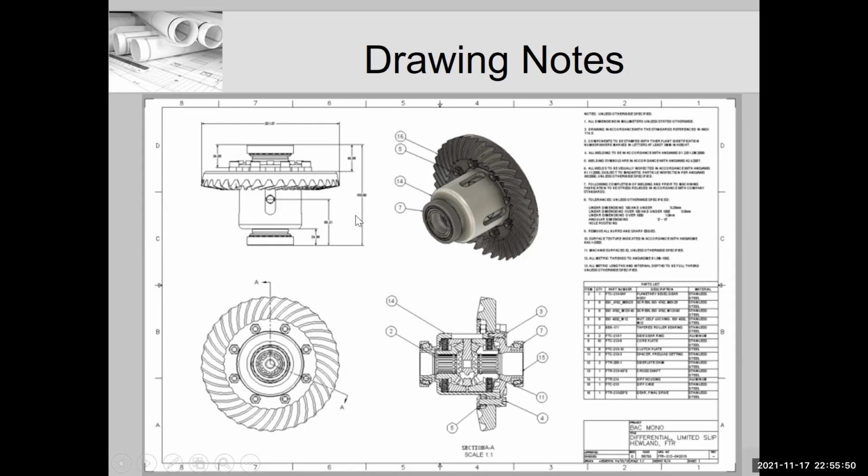Reference means in parentheses, so that someone putting this together says they wanted to measure it with a set of calipers and they say, oh, I'm close to this. That's what I'm supposed to be at. And if they're not close to it, then they need to tighten some pieces up. So this overall dimension here makes sense to me. This one here may also make sense in the same context, and the placement of this particular hole in reference to the slot makes some sense.